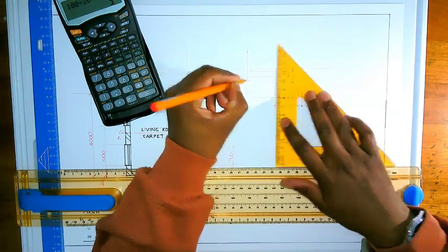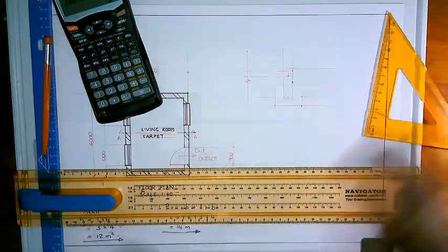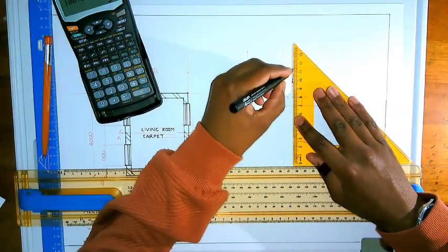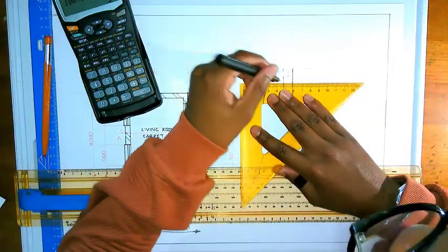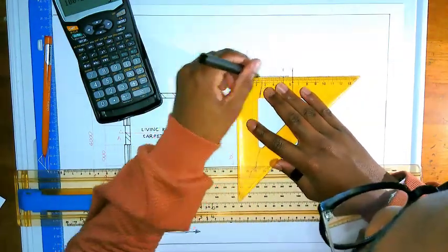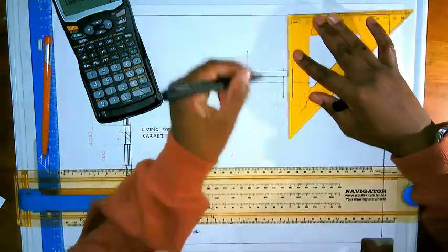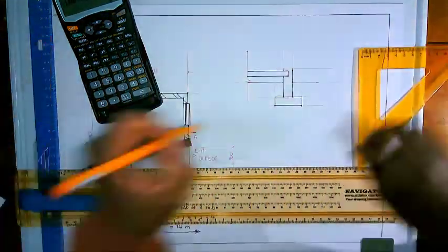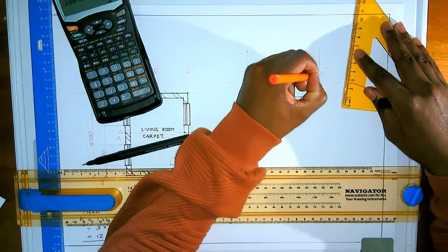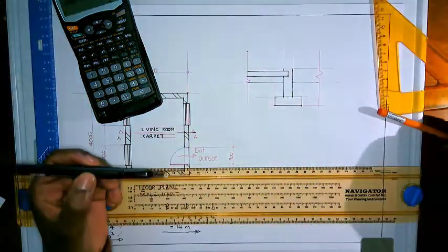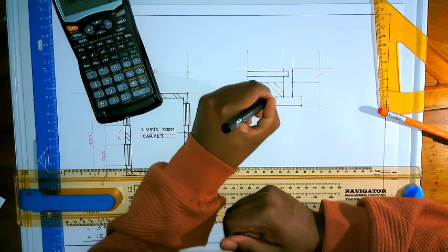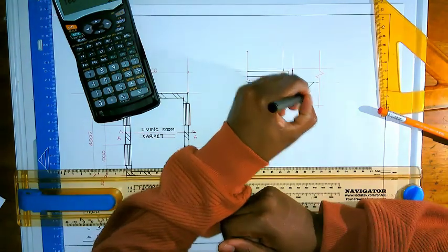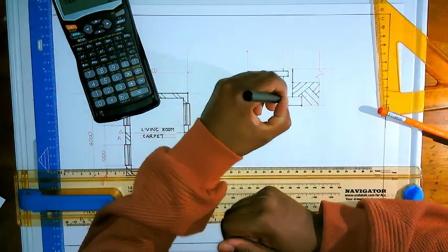Now that I'm done drawing my actual sectional elevation, it's important to now place hatch lines that indicate the different parts of the section. That is the foundation, the concrete slab, the earth, the compact hardcore. Look at how I'm going to be doing those freehand, and you should rather apply the same principles. Again, pay attention to how I'm drawing neatly and I'm drawing correctly.